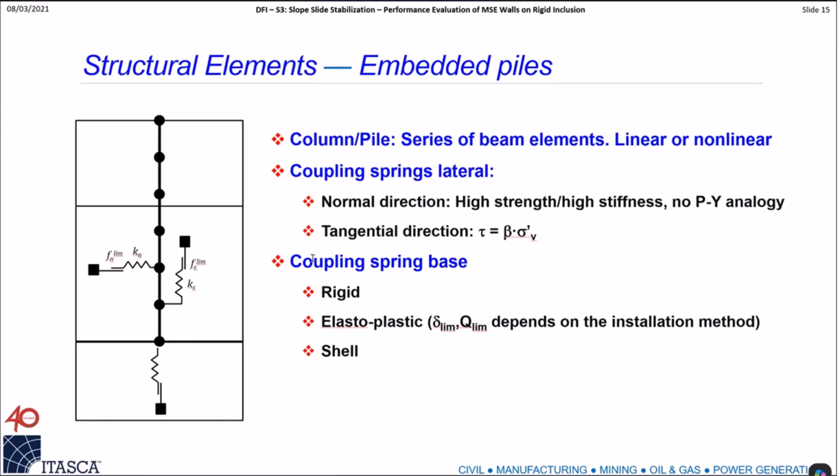Now, I mentioned that there is a distinction between the vertical and the horizontal. All that we have talked about for now is the horizontal. When you push a pile into the ground horizontally, you have a volume of reaction, which is somehow related to the diameter of the pile. As we have seen in the other numerical example, you have this volume, which could be 1 diameter, 1.5 diameters. It tends to dissipate with depth and whatnot. But you have a relatively large volume of soil that reacts to the force that we apply to the pile.